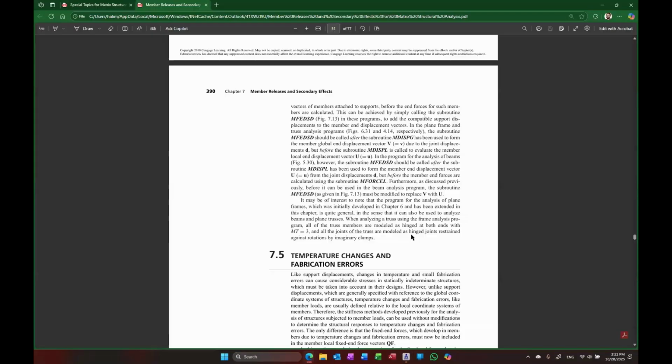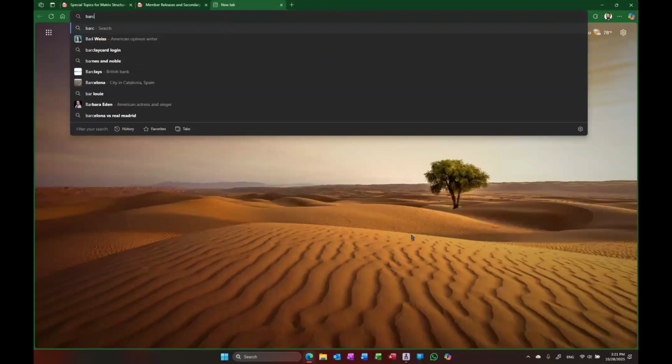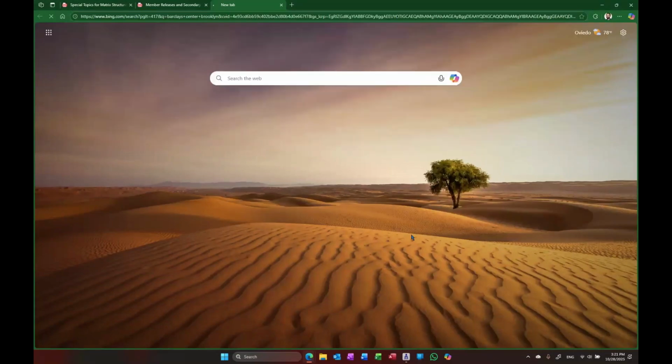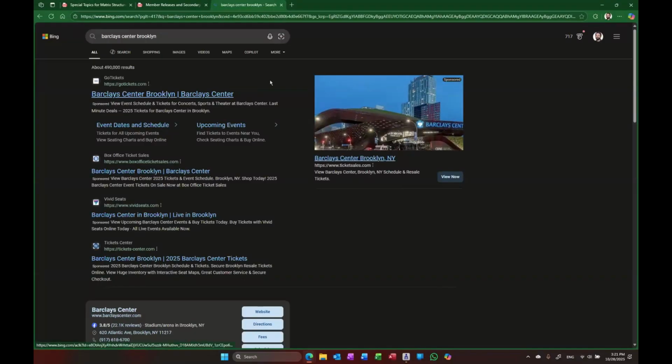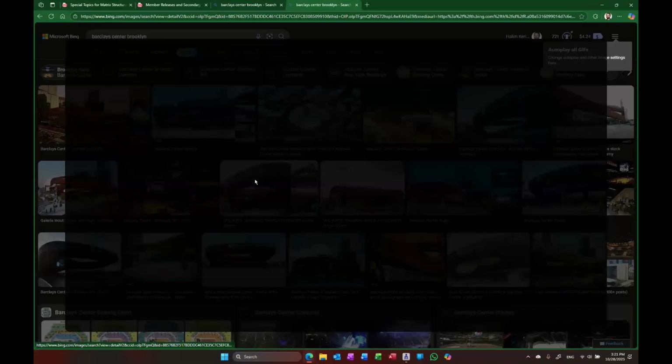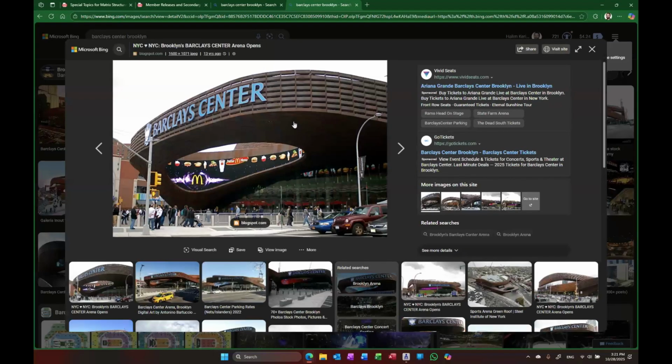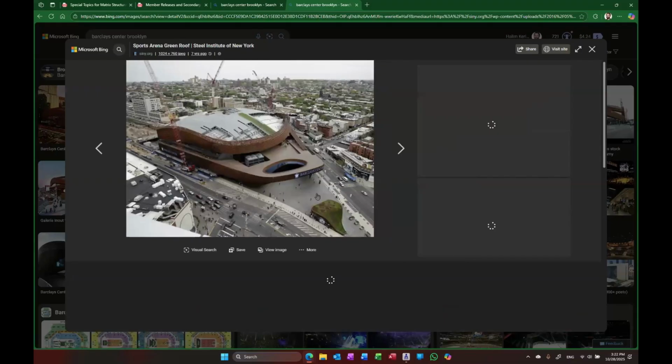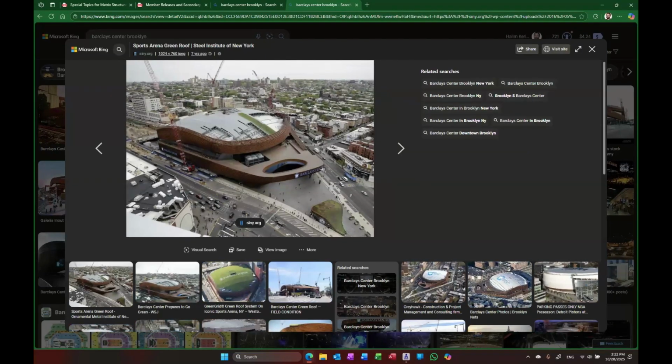They basically designed it so, let me show you. This cantilever here, they designed it so it was actually pointing up initially, and after all of the load was put on it, this long cantilever came back to its original design dimensions.